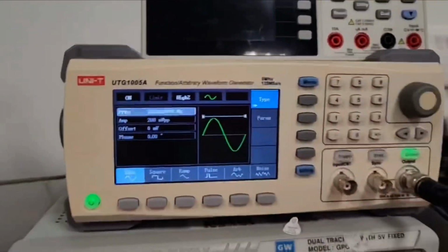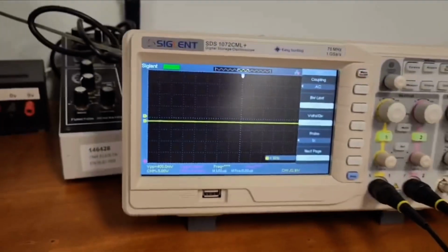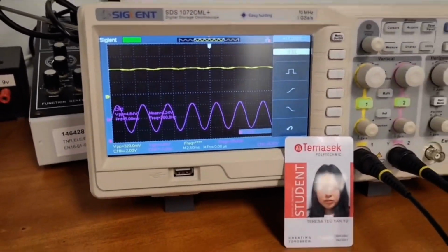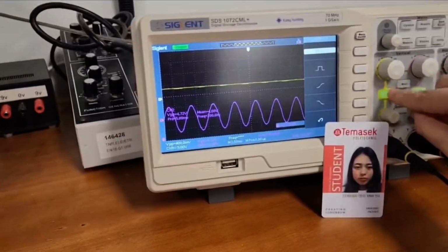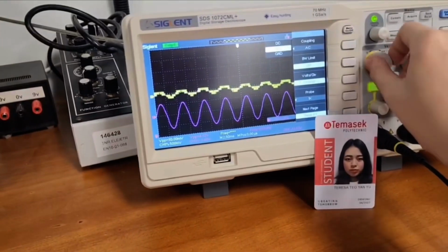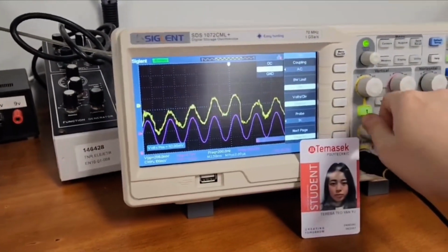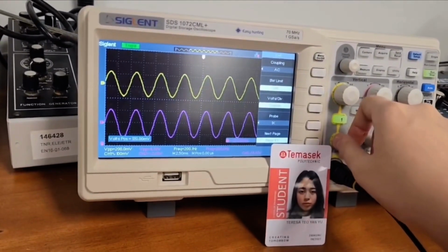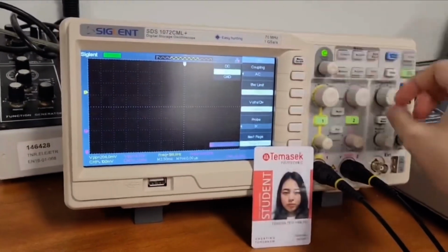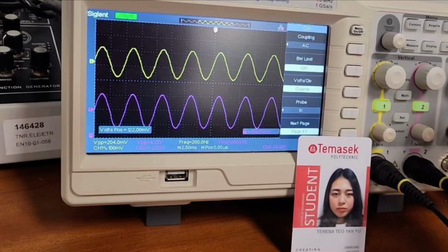Now, the only thing that I will change is the frequency, which will be put at 200 Hz. The voltage output amplification is more drastic, from 200 mV to 4.72 volts, because the gain has increased. The gain at 200 Hz is higher than at 1000 Hz because 200 Hz is comfortably within the bandpass filter's passband, while 1000 Hz is at the edge or outside. Bandwidth will be elaborated on later.